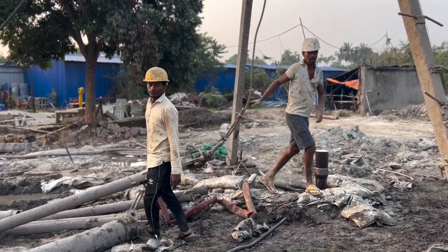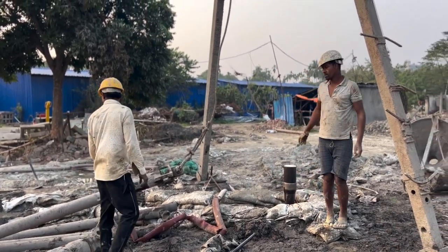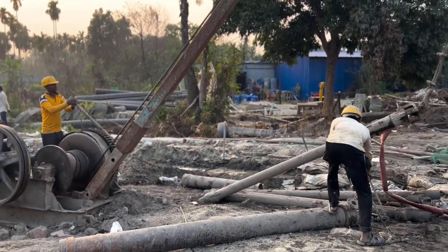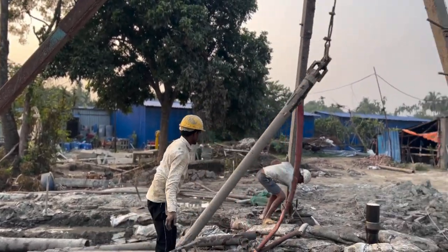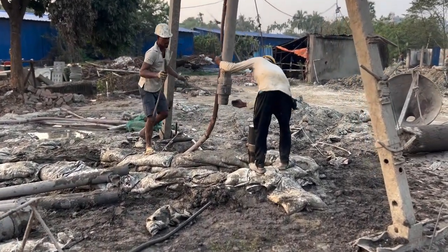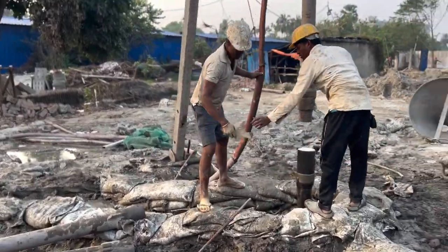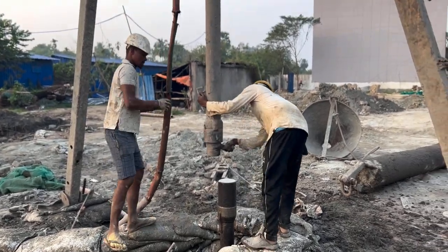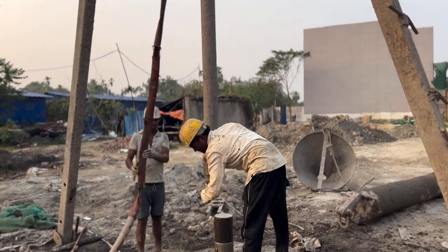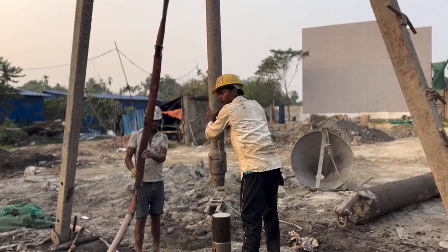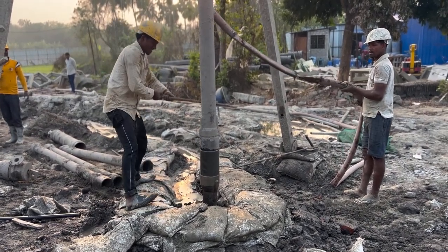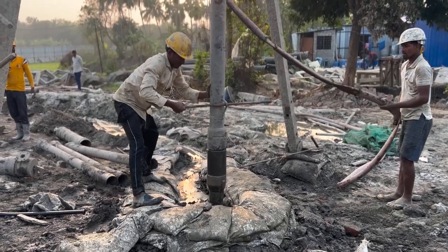It involves drilling a borehole into the ground using the DMC method, that is direct mud circulation method, and filling it with reinforced concrete after removing the loose soil using bentonite slurry. So why is bentonite slurry used? To stabilize the bore. Otherwise the bore will collapse, and if the bore collapses, we are not serving the purpose. You cannot do the concrete, and the pile will not go onto the strata where it was actually designed for. That is why we use bentonite slurry to stabilize the bore diameter or the borehole. So this is about what is DMC bore pile.